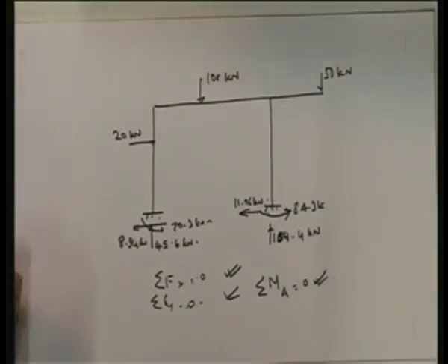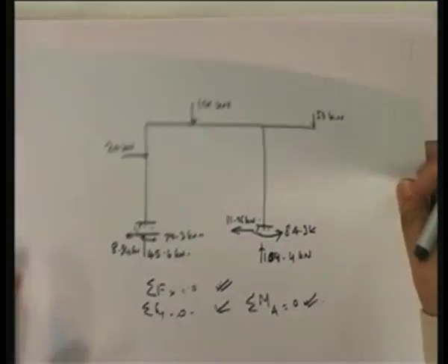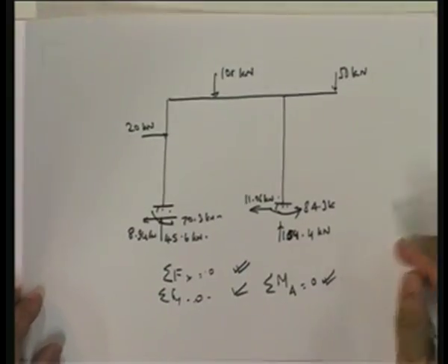And ultimately, the solution that I have given to you is identical to the one that we computed using the displacement method. So essentially the moment distribution method, if applied using sway and non-sway distributions together, you will get the final solution.